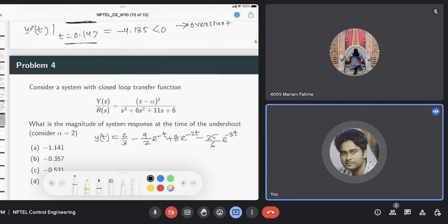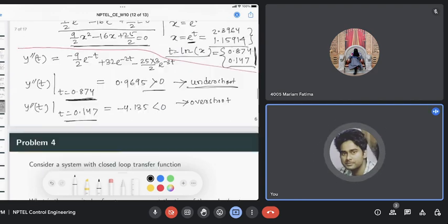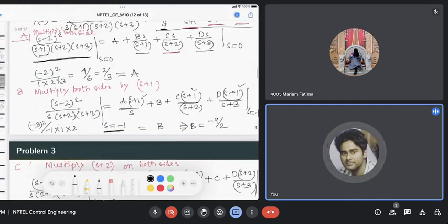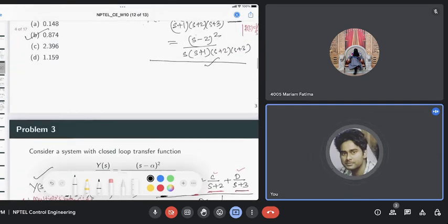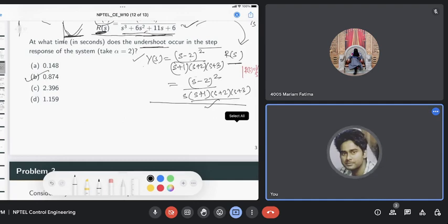You can also check whether this is correct or not. One thing I can mention here, because of this factorization, your poles will be such that for s it will be a constant term, for s plus 1 you should have a response like e to the power minus t, for s plus 2 e to the power minus 2t, and e to the power minus 3t, right?